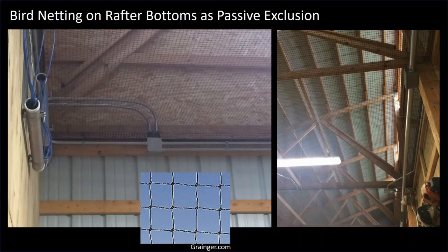This is an example of using bird netting. Oftentimes we experience wash pack areas being built into barns or existing spaces, maybe where birds have been residents longer than the current owners. So, how do we exclude birds from a barn area where you need to be handling fresh produce? One way of doing this is by using bird netting. This is typically used in the field for bird exclusion, but it can certainly be applied inside of buildings. What it does is make the rafters not a very hospitable place for birds to roost. So it's a pretty economical, simple, passive solution to keep birds from roosting overhead.